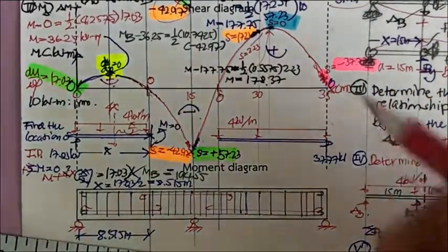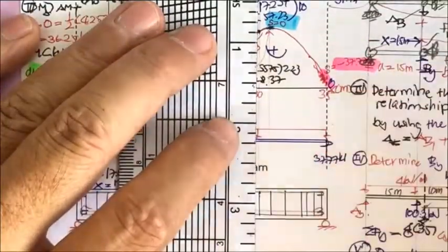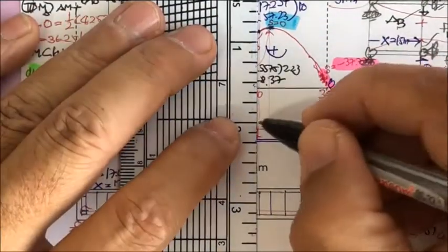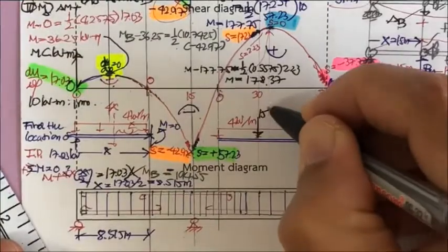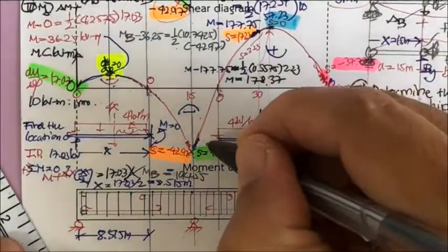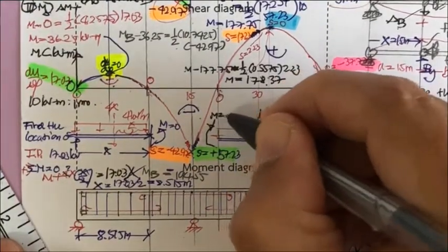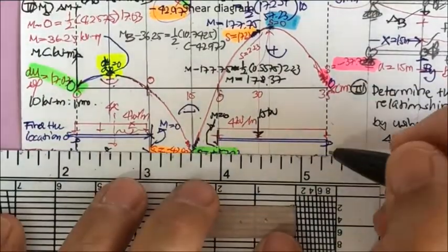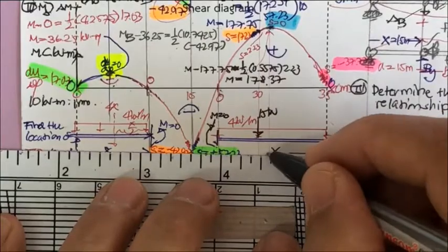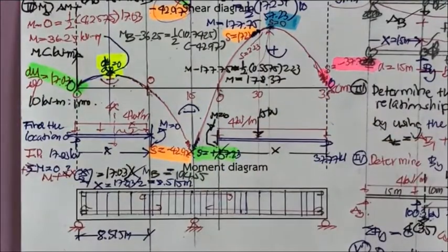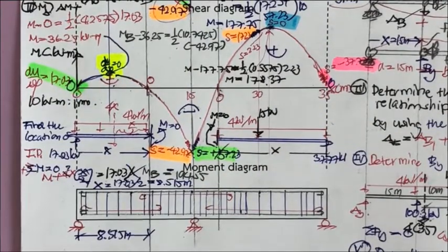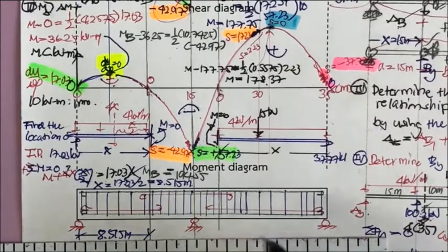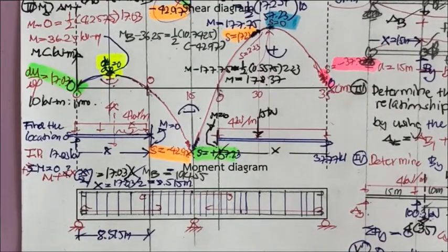And at the median, you have 15 kilonewton. Okay, again, the moment here is going to be 0. And then if you take here, you can determine the distance x here easily. So you can get the location for the inflection point where you change the reinforcement.